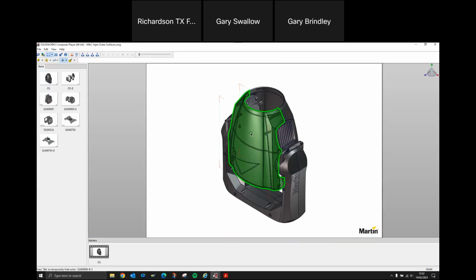but in the bottom left-hand corner, you can see it says 6240-9808-B-2. Now, the -B-2 is not part of this part number. That is internal R&D references of revisions and model revisions that they've made. They may have multiple versions of this same part in the same model. They're just hiding them from public view, but they've left that as the name. So sometimes that bottom left-hand corner is more confusing than anything else.